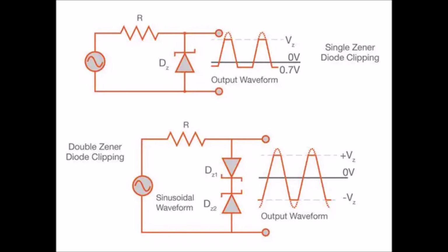Here's another definition of the same thing. Here's definition 2 of a Zener diode. A Zener diode is a special kind of diode which permits current to flow in the forward direction as normal, but will also allow it to flow in the reverse direction when the voltage is above a certain value. The breakdown voltage known as the Zener voltage.